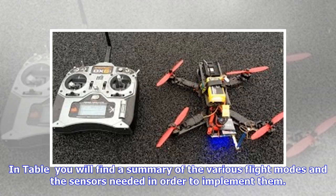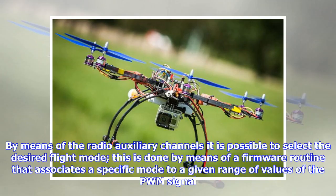In the table you will find a summary of the various flight modes and the sensors needed in order to implement them. By means of the radio auxiliary channels it is possible to select the desired flight mode. This is done by means of a firmware routine that associates a specific mode to a given range of values